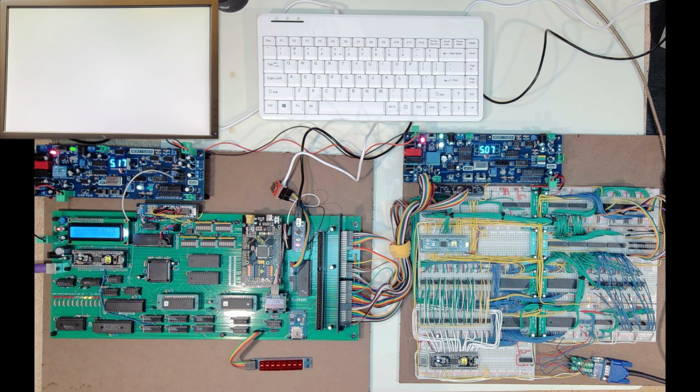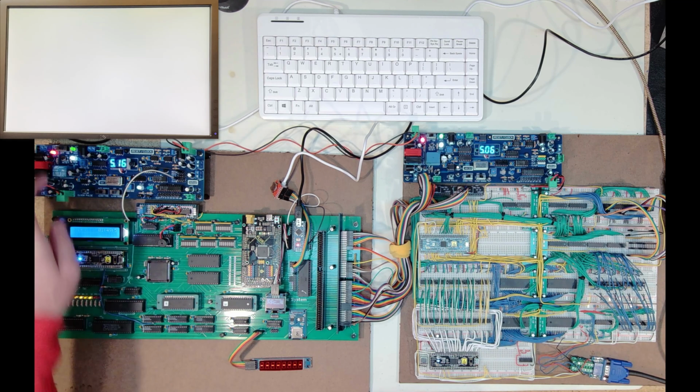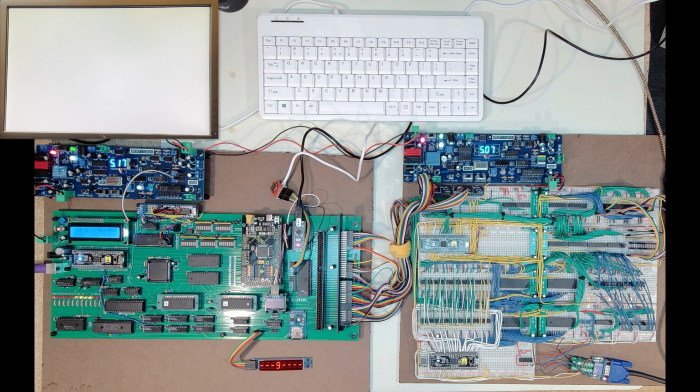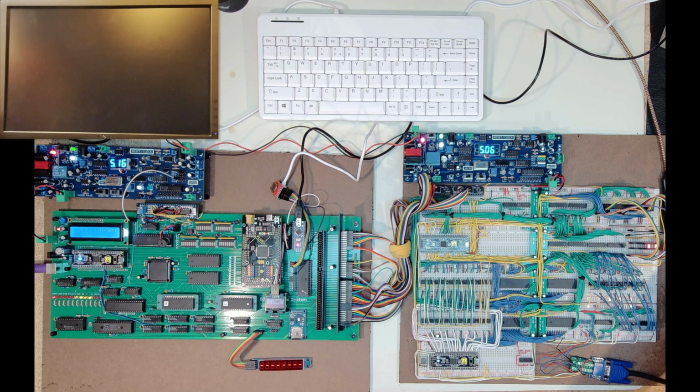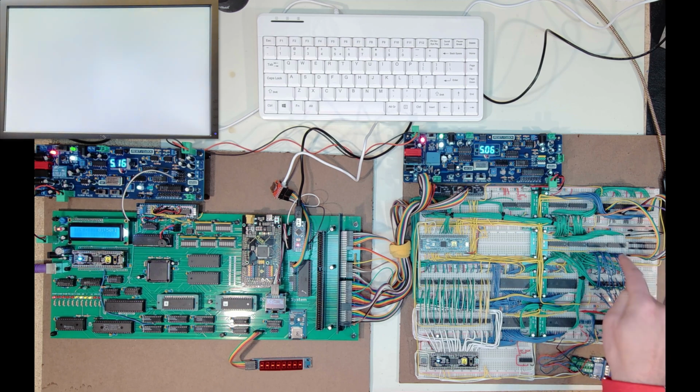So when I reset this, it's going to go through my normal RAM testing, then I'll see it gets over into the VRAM, and there it went through one frame. I saw it toggle to the other, so there was a momentary wait for the VSync, and then I saw it flip through the other frame. So I'll do that again if you want to watch that. But it's going to flip through my segments, flip to the other frame, flip through the segments, and in between both of those you saw that quick little pulse while it was waiting to flip frames.